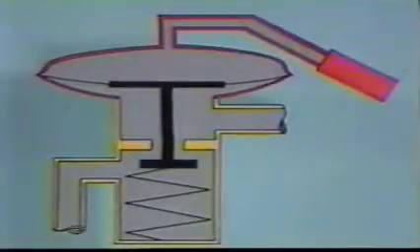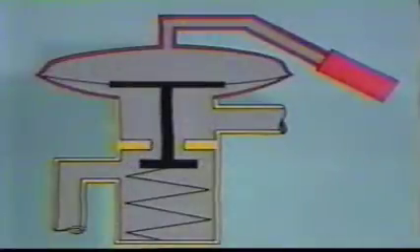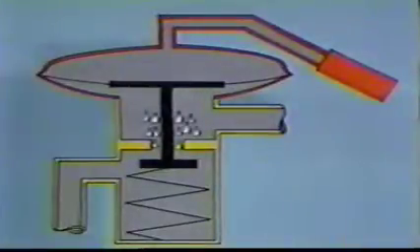Expansion valves, for example, are made up of a number of close tolerance parts that must be free to operate smoothly and evenly. The orifice, by its basic purpose, must be small. It doesn't take much contamination to shut a TEV down. Water that has been dissolved in refrigerant can condense and freeze if allowed to reach the valve orifice. The resulting ice crystals will clog the orifice and cause starvation of the evaporator. Clogging can also come from the other contaminants, whether they be wax, metal, or sludge. All small orifices, regardless of location, must never see these contaminants.